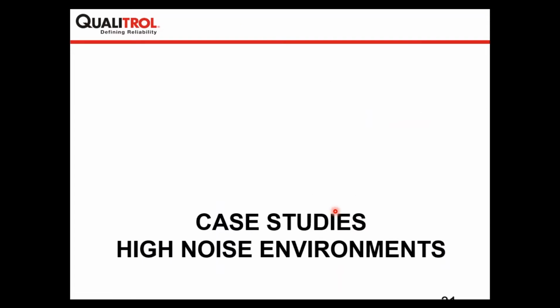If you have experience with online partial discharge measurement, or if you read the literature, the biggest challenge for performing online partial discharge measurement is the external noise or the system noise which is present inside the system. So here I will be presenting some case studies which will help you understand how we are separating out different activities and classifying them as partial discharge or noise.